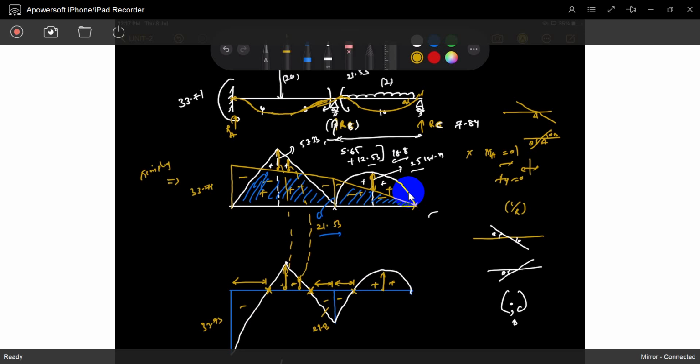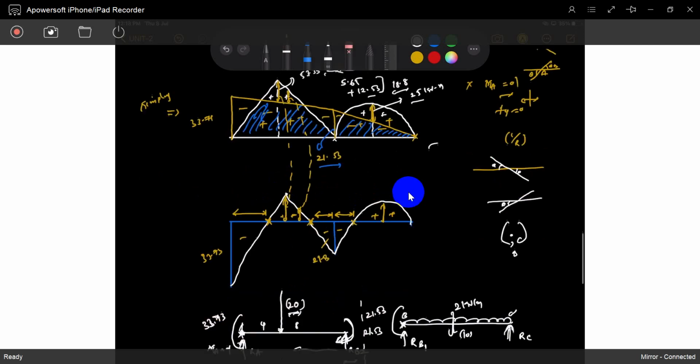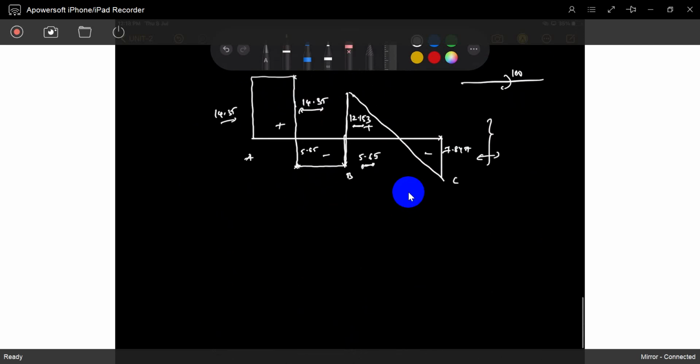So if any problem is given to analyze the beam, you have to find the moments, reactions, shear force diagram, and bending moment diagram. Later, if you draw a curvature diagram also based on the points of contraflexure, that is the completion. I will show you how to draw it. Understood? That is the story of one problem. Now I will solve another problem, which is very easy. Just see it.